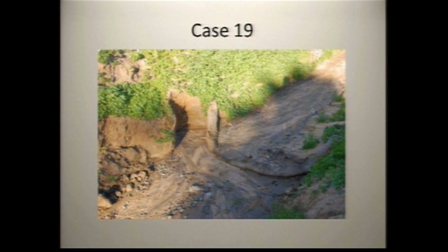What about this? It's a straw wattle used as a check dam. Does it look like a good idea? No. I mean, straw wattles aren't permeable enough and aren't the right tool to be used as a check dam, which should be riprap that has a downstream landing pad and be keyed into the sides. So if you see stuff like this, it's doing more harm than good, and just make them take it out.